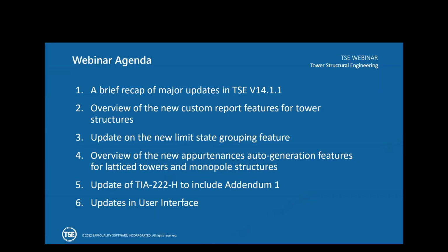So what we are going to see today: first we are going to do a brief recap of the major updates in this version. Then we will see the new feature of custom report, and we'll do a live demonstration to show all the features that we added to TSE, including the custom tables and also the grouping feature. And I will also touch on the auto generation of appurtenances for latticed tower and monopole structures.